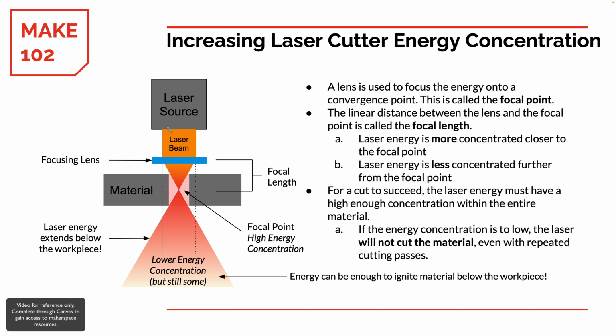A few things to note: once the beam goes through the material, there is still laser energy below the part. This can be a problem because there can be things below the part, like the support material holding the part, or small pieces from previous cuts. So we have to be mindful of what is below our part.